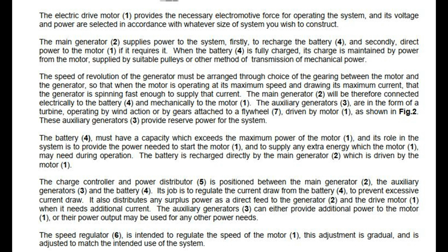The battery, 4, must have a capacity which exceeds the maximum power of the motor, 1, and its role in the system is to provide the power needed to start the motor, 1, and to supply any extra energy which the motor, 1, may need during operation. The battery is recharged directly by the main generator, 2, which is driven by the motor, 1.